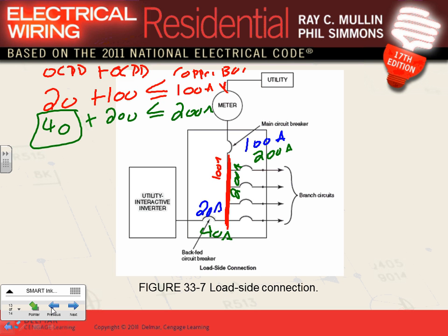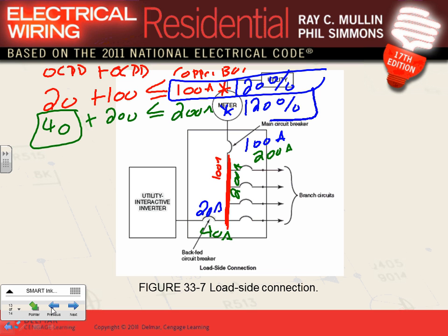You're with me. I just forgot one little multiplier here, guys. 120%. I'm so sorry. 120%. My sincere apology. Now, does it make sense? Yeah. Okay. So now, does that make sense? That's what the requirement is. So when you add these two together, it has to be equal or less than 100, the bus, multiplied by 120%. So you can't add more than 20% on the bus, right?